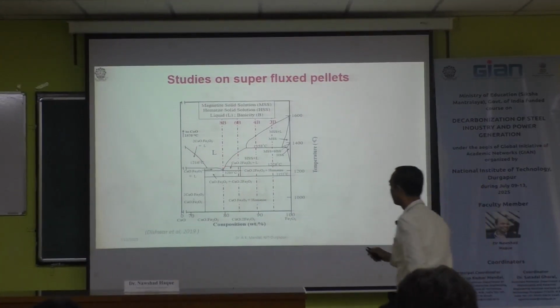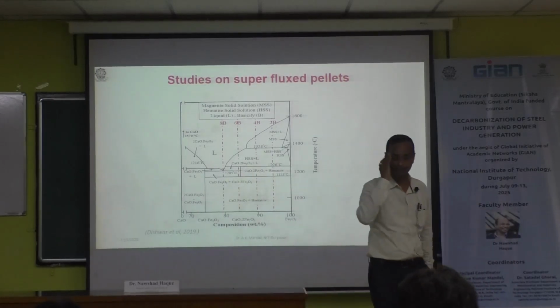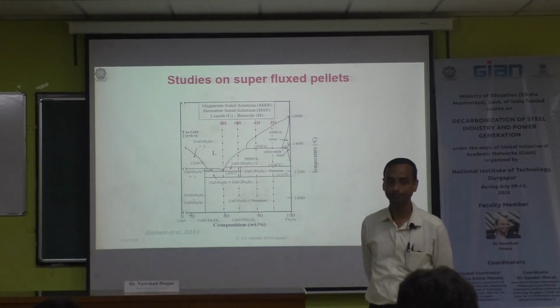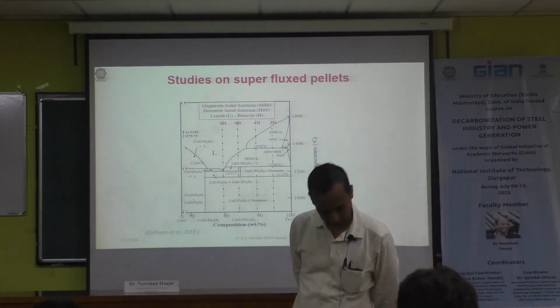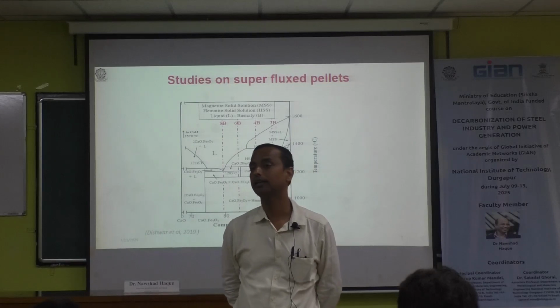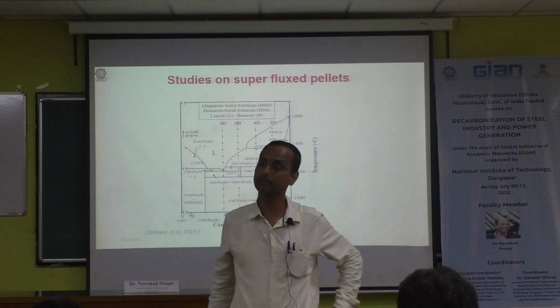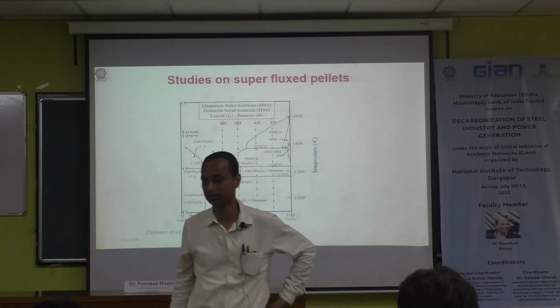You can have 1200 degrees Celsius, because that is the composition of the primary slag inside the blast furnace. It is the critical temperature where you can heat. That means if you can heat at 1200 degrees centigrade, yes, it will form that compound.